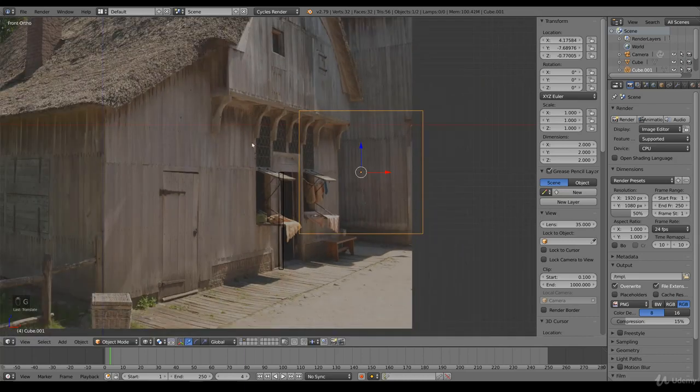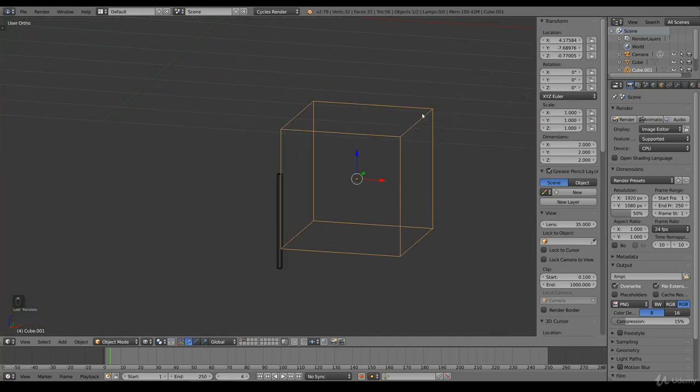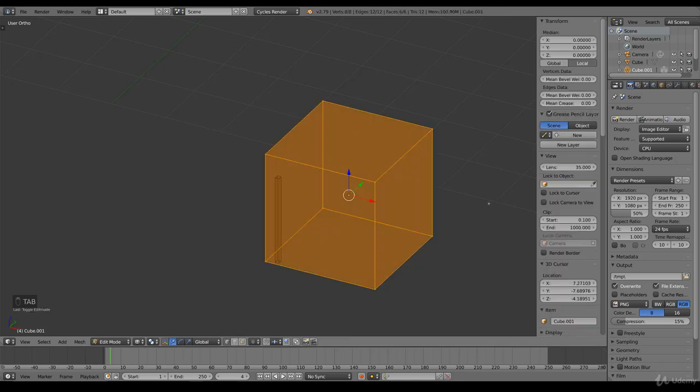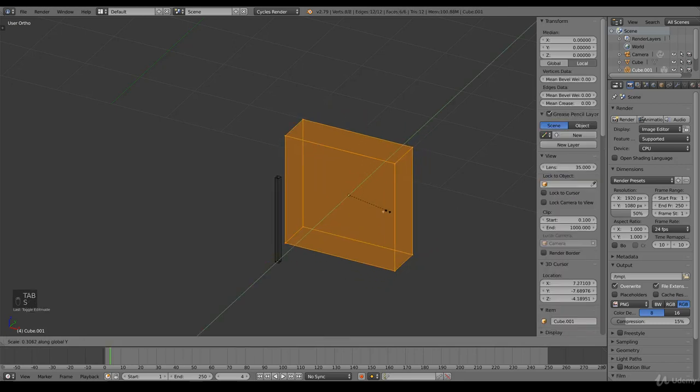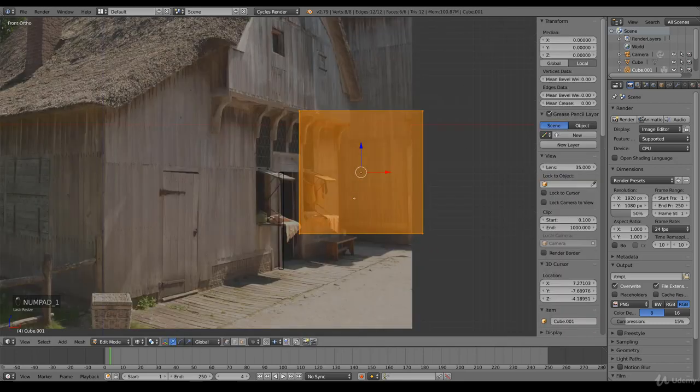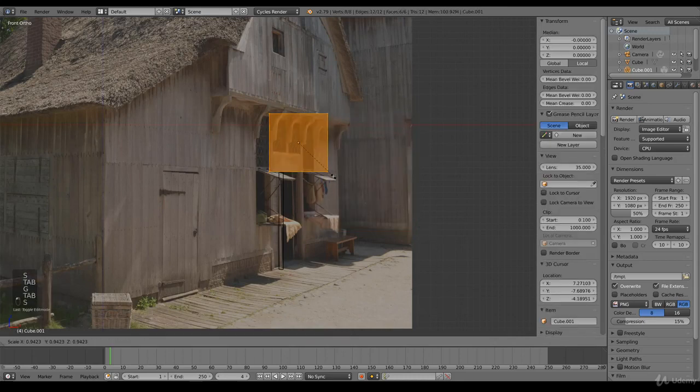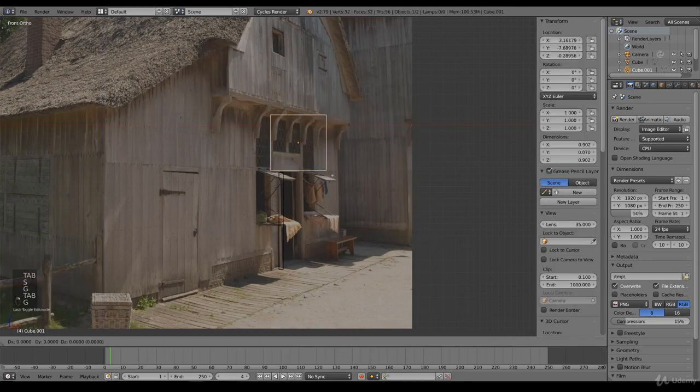You can see this looks rectangular, but we are going to adjust the look later. First, we need to prepare this window frame. So turn around, edit mode, S, Y, front view, scale this a little bit, having it about the same size.